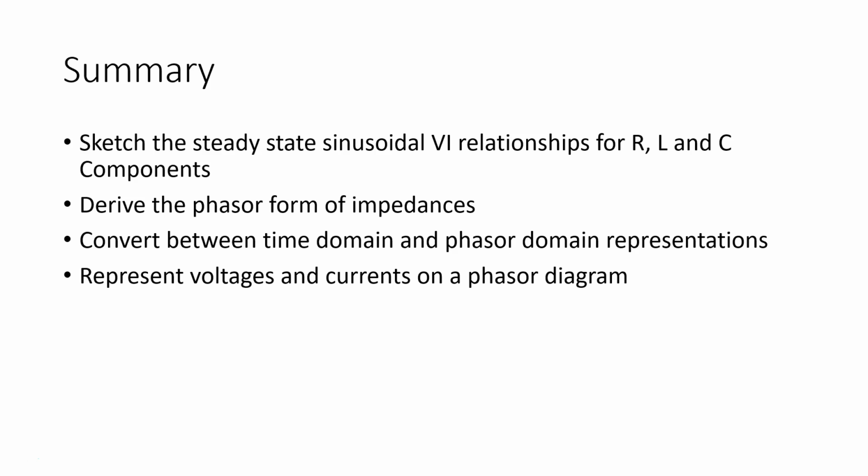Just to summarize, you have to be able to sketch the steady-state sinusoidal voltages for R, L and C components. You have to know how to derive the phasor form of the impedances, which is just changing to the complex exponential notation and looking at the value of Z. You need to convert between the time domain and phasor domain representations, which is just pulling out the RMS value and the phase from your sinusoidal representation and putting it into phasor form.